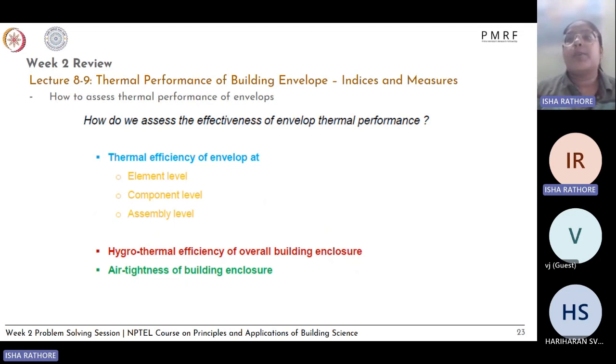For example, your building can have leaks, or because of poor workmanship, there could be gaps around your windows from where air can be coming in. These are very small gaps, but they affect the thermal performance of your building, especially in winters, when you want the heat from the inside to not escape out, because the outside is at a lower temperature and it will transfer heat from inside to outside, as well as wind flowing in from outside through these gaps or leaks in your building construction.